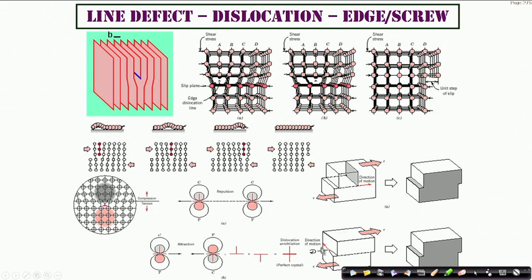If you imagine a helical path around a particular line, which happens because of the twisting or shearing of this crystal along this particular axis of rotation, then this is how you can create a screw dislocation. So essentially we have line defects, either as edge or screw.